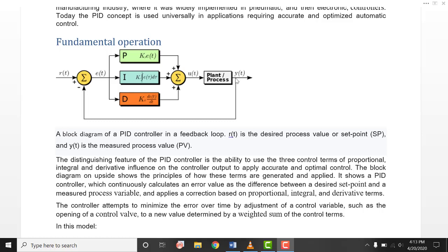Okay. At our achieved output value, we have another feedback system, which will again help to create another error. For example, you have 100 value over here, and here you get 80 liters per minute, let's say. So this 80 will again come back to this feedback system. It will then be subtracted from this value, and now this error e(t) will be 20. So Kp, Ki, and Kd will act as coefficient factors, which will change the value of this error with respect to time.